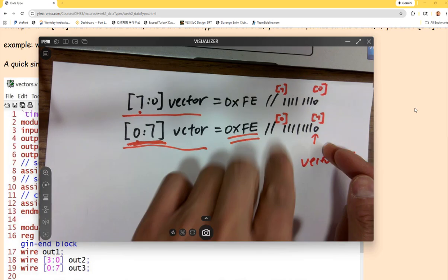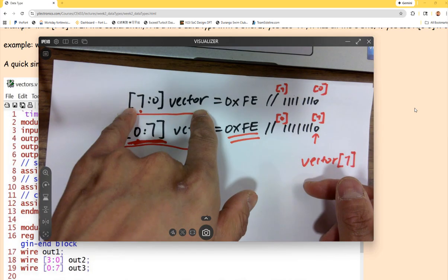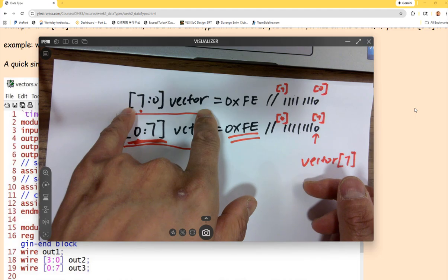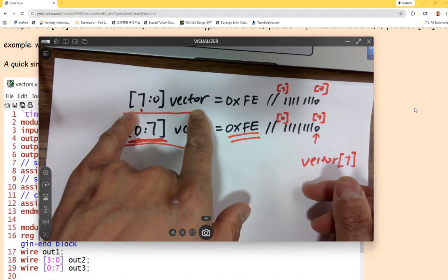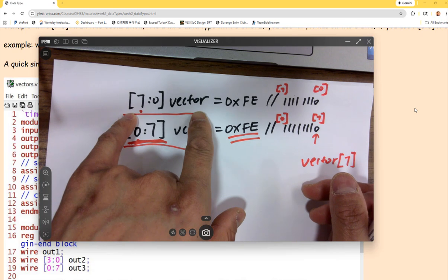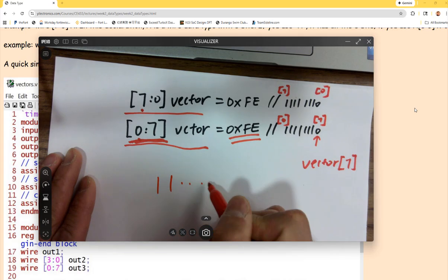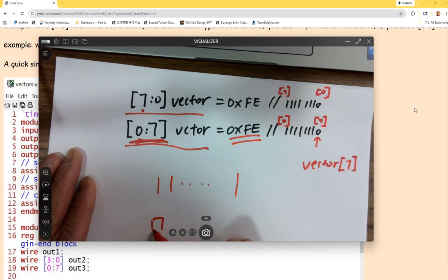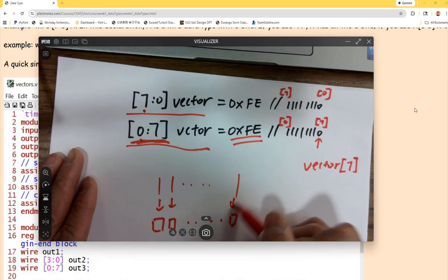Yeah. So this is just making up a vector, right? And if you make a vector, it's actually a space. So for this vector, it's basically just 8 flip-flops, because they're able to hold the data there. When you are assigning its parallel data over here, you get 8 parallel data and you have 8 flip-flops. It just directly assigns these values to these latches or flip-flops.